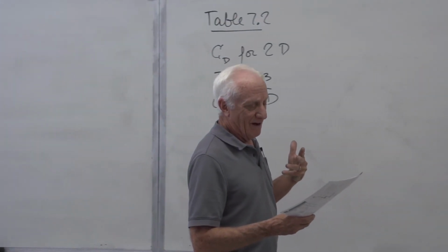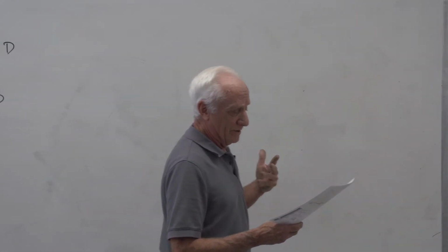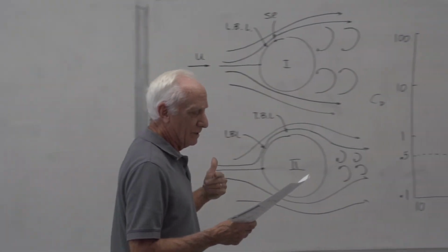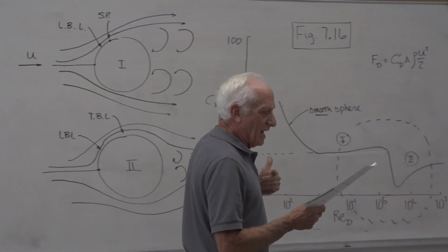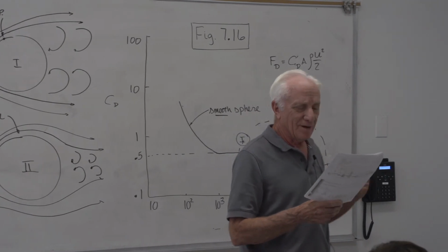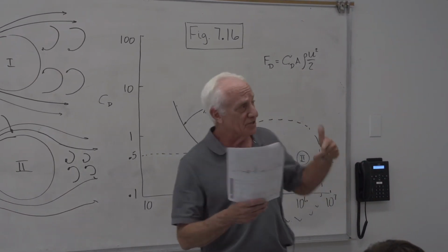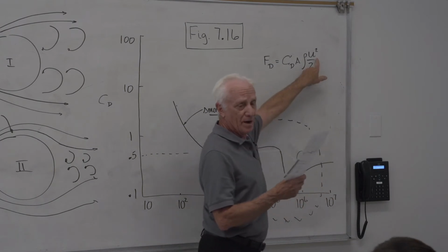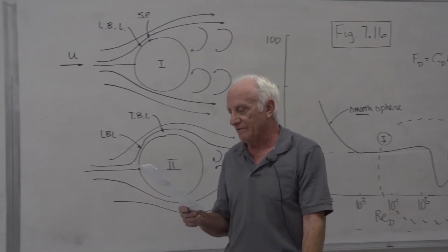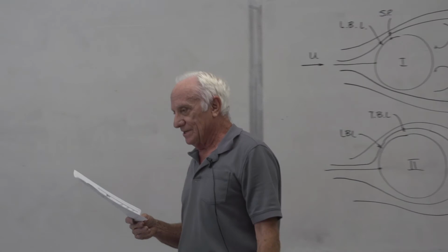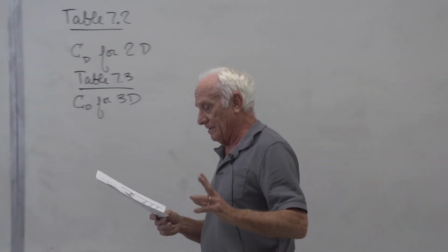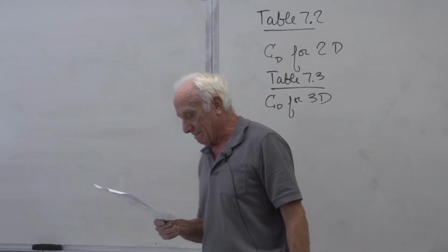If you're going 5, 10 miles an hour, there's not a lot of air resistance. Most of it's friction. As that truck passes about 60 miles an hour, the air resistance picks up dramatically because it's the square of the velocity, a parabolic shape. And so the air resistance becomes very, very big.